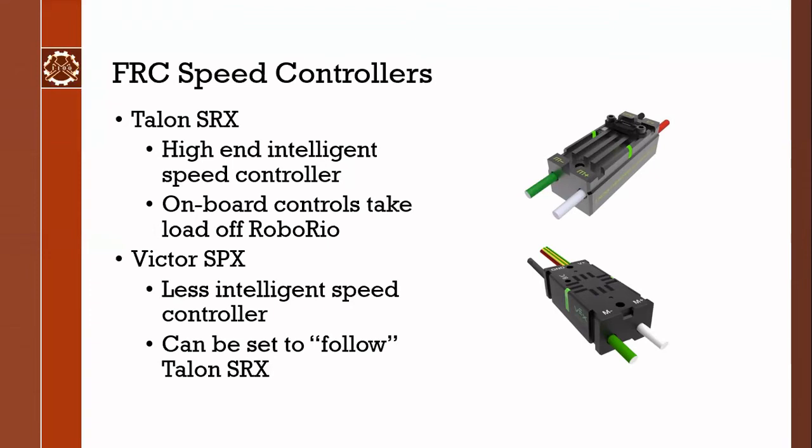So the PWM and CAN is very, very small amounts of power, very low voltage, whereas the 12 volts is like big, thick wires, meaning it's going to have a lot of current, and it takes a lot of energy to actually spin a motor. The speed controllers are a way to both separate your signal and your power lines, and to add the intelligence to decode the signal and get the gate in the speed controller to do cool things.